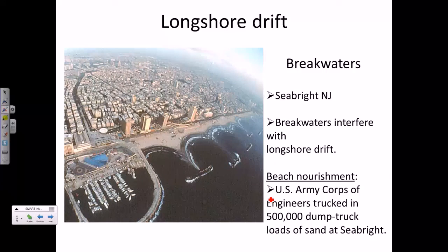Here's breakwaters along the Jersey shore. So there's a breakwater, there's a breakwater, there's a breakwater, and so the wave energy is deflected, or bent, or refracted, if you will, and bent around these, and then scooches in towards the center like this, and towards the center, and builds out the beach toward the breakwater.